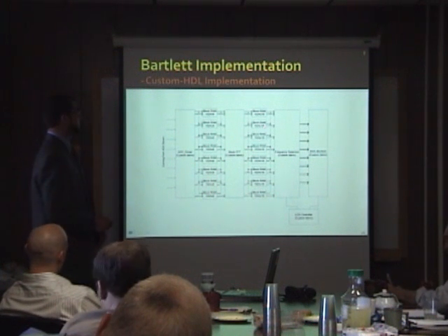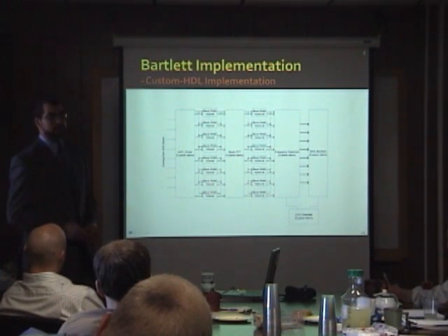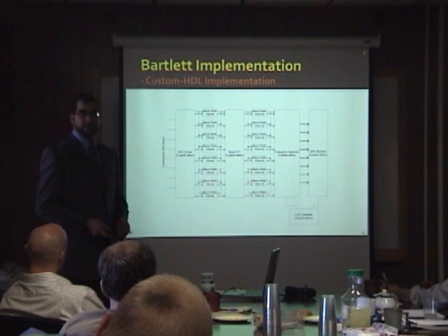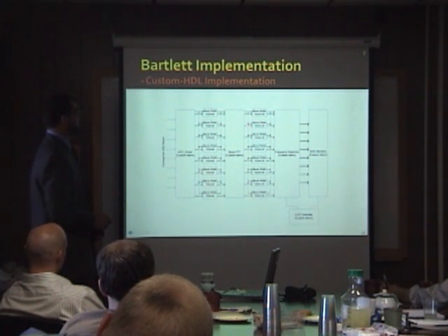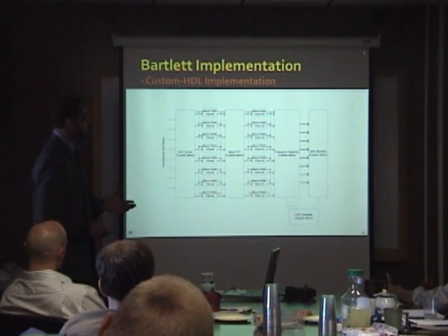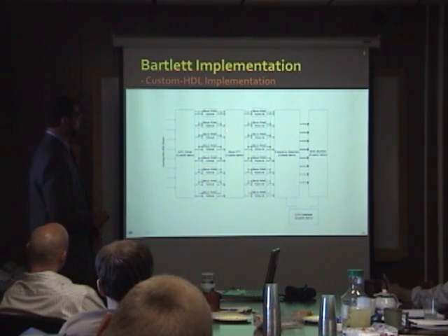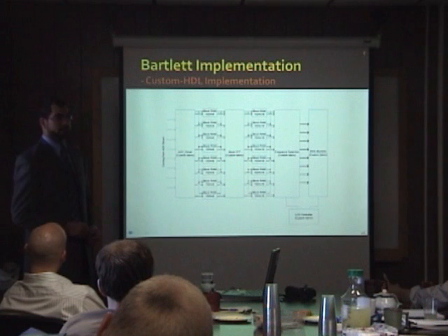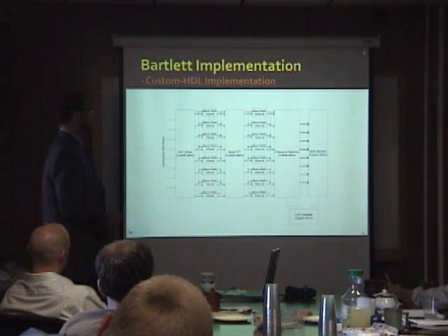The reason it's 18 is because the results of the FFT contain real and imaginary data, and each is 9 bits because this data is unsigned. So we do a sign extension and then perform the FFT. The output is 9 bits per either real or imaginary.